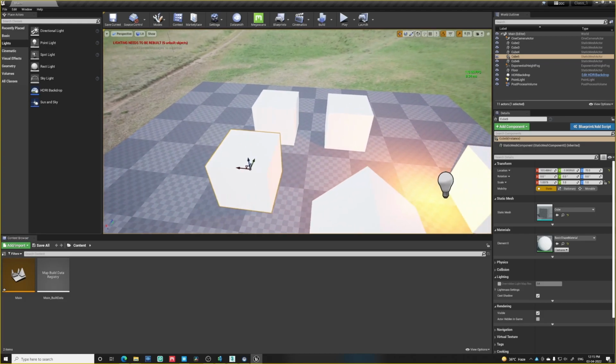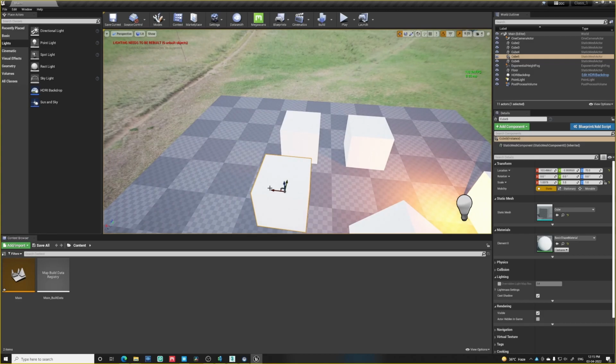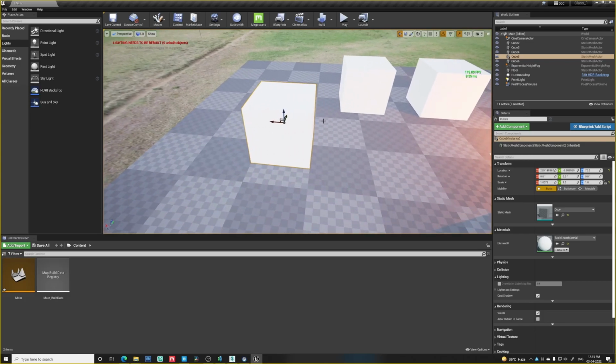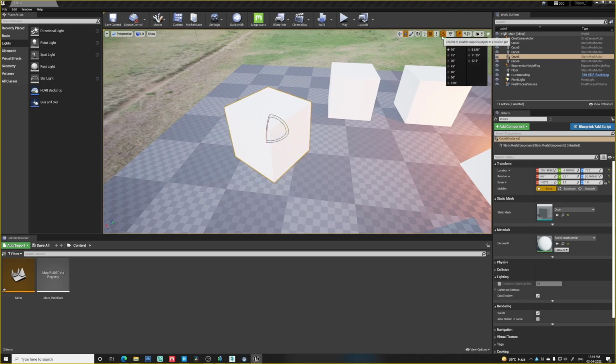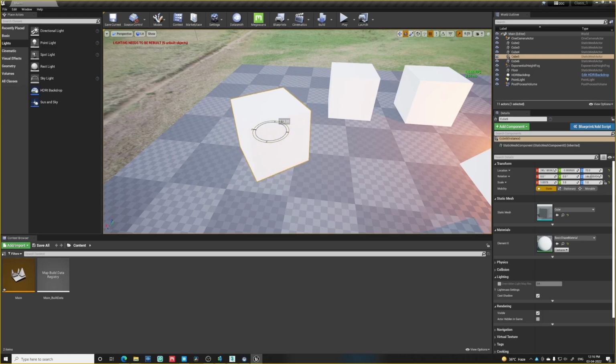No, this feature doesn't have the option to align with the object. Yeah, Max has this good feature that you can align with the object and you can align with the vertices. Right. So this has also grid snapping. This is also rotate snapping. It's now rotating on 10, 30, 40, 50, and you can change it to any degree, or you can just turn this off. So now it's smoothly rotating. This is the same thing with the rotation, or scale for the scale snapping. Yeah. So is this clear?